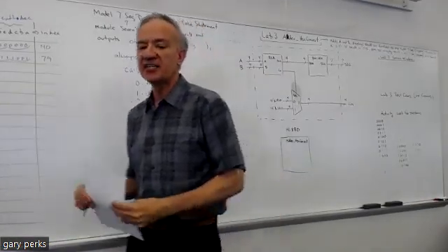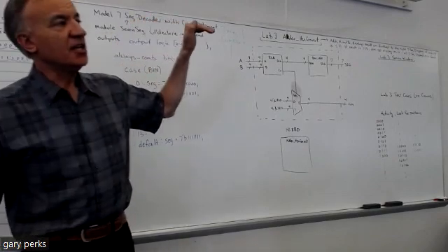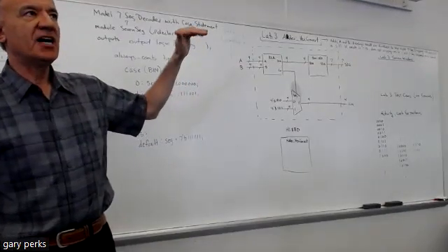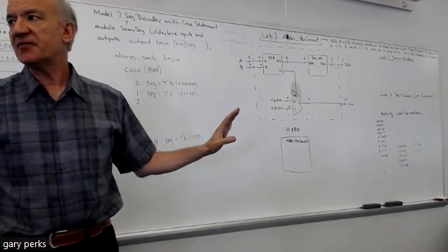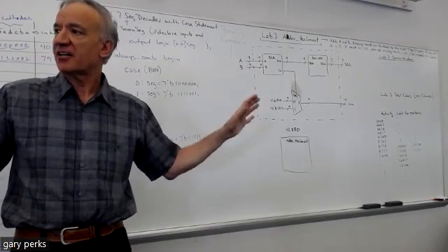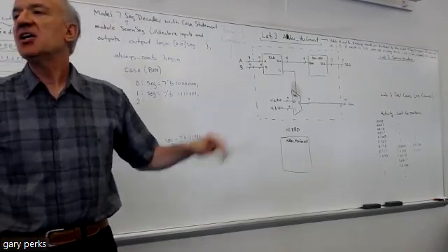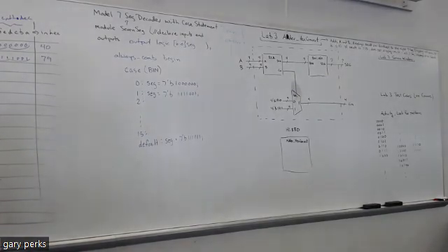Now, the thing I didn't mention last class when we were talking about building the mux with an if statement, and if statements in general, is that you need an if, and you can have as many else ifs as you want, or you don't have to have any. So else ifs are kind of optional, a wild card kind of thing. And then there's the else. Well, in an if statement, if you don't have an else, it creates a latch. That's the thing I forgot to mention last class.